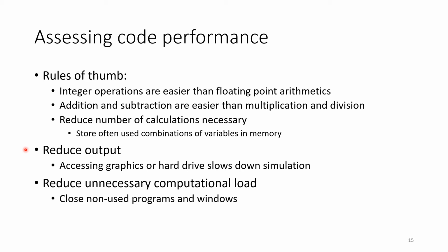Also, saving to the hard drive takes time, because the same thing happens. Your CPU stops with the calculation, talks to the main board, talks to the hard drive, and the commands are executed on operating system level, stuff like this. It takes time. And of course, sometimes it's necessary, no question, but make it reasonable, right? Not putting out a million times the same results for different time steps, but say, okay, I might have a time step of an hour, but I'm actually just caring how it looks at the end of the day. So you're just saving every 25th time step.